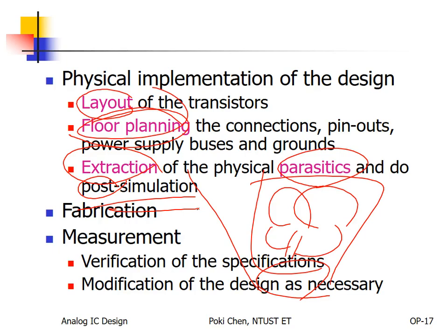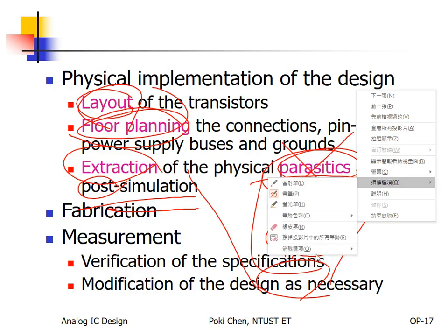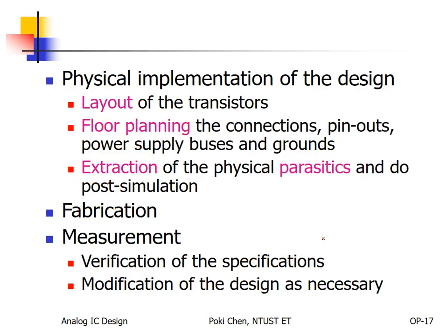The major difference between pre-sim and post-sim is parasitics. If you simulate your circuit with all the parasitics you extracted, then it is for post-simulation. But even after layout, you can do the same simulation without parasitics. Then forget about it. The result should be exactly the same as the pre-simulation.